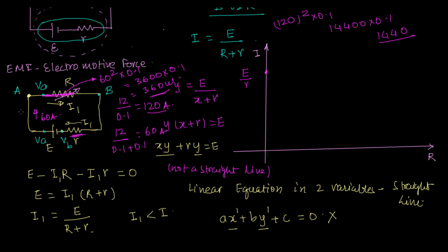One of them is an overcurrent relay that you can use. So the moment it senses a current, say more than 30 amperes or 40 amperes, it'll cut the supply. Correct? But I'm just telling you what you should expect. Had this R not been there, and if you would have shorted it with zero resistance, it would have started carrying an infinite amount of current.